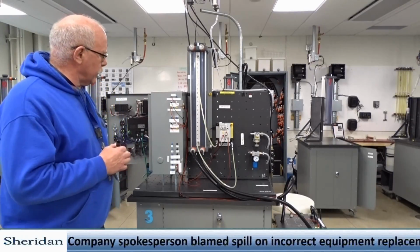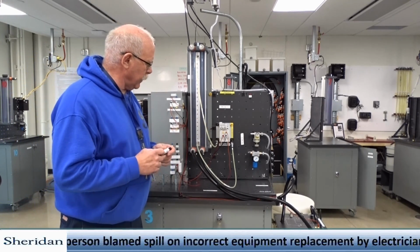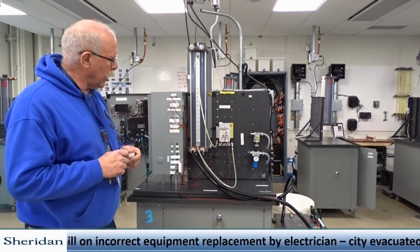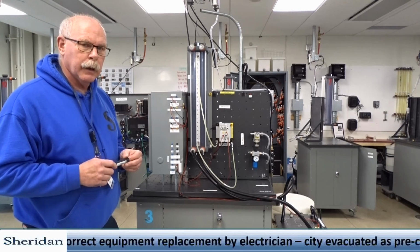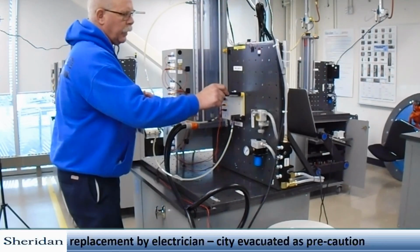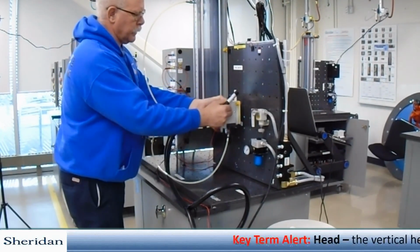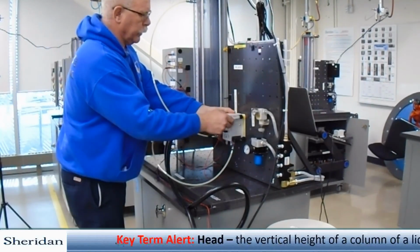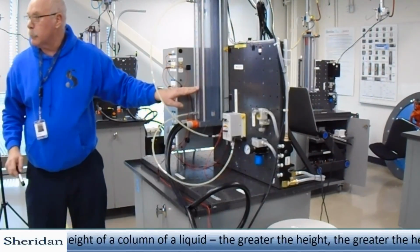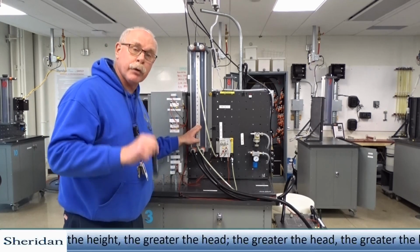Now what we're going to see is what happens with this type of level measurement, using a pressure transmitter. I'm going to move the pressure transmitter, and I'm going to see what the effect is on the level. So, undo it. I move it sideways, I drop it down, and what you'll see is that the level has now dropped. I move the transmitter down, the level dropped. The reason being is it's measuring pressure.